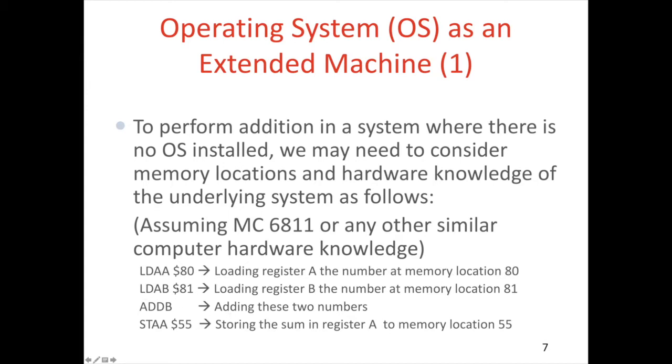LDAB address 81: loading register B with the number at memory location 81. ADDB: adding these two numbers. STAA address 55: storing the sum in register A to memory location 55.